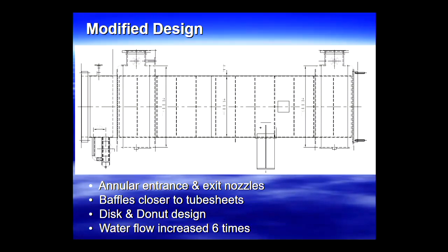The net effect of that was that it brought the temperature in the metal down by around about 20 degrees, which brought it within its capability, so it stopped corroding. And that vessel is still operating today. It fitted in the same space that the original one did, by the way. That's quite a tricky task.